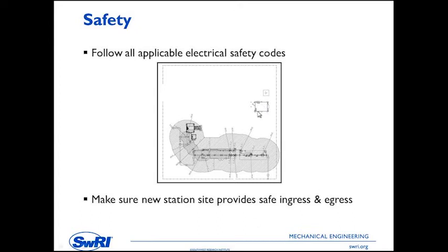The National Electric Code has requirements for assigning hazardous area locations. The close proximity to the piping and the flanges would be classified as Class 1 Div 1, and then there's a radial distance beyond that that's classified as Class 1 Div 2. Over here where this building is situated, that would be an unclassified building, and so there would be no hazardous rating to anything there. Appropriate seals have to be applied in the conduit, though, to isolate between those different hazardous ratings.